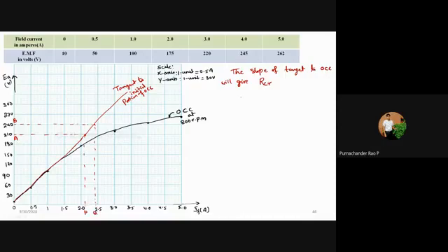So your critical field resistance RCR is equal to the voltage AB divided by the current, this is the field current PQ. B point is 240 and A is 210, so 240 minus 210 divided by 2.4 minus 2.1, because these points are 2.1 and 2.4 amperes.